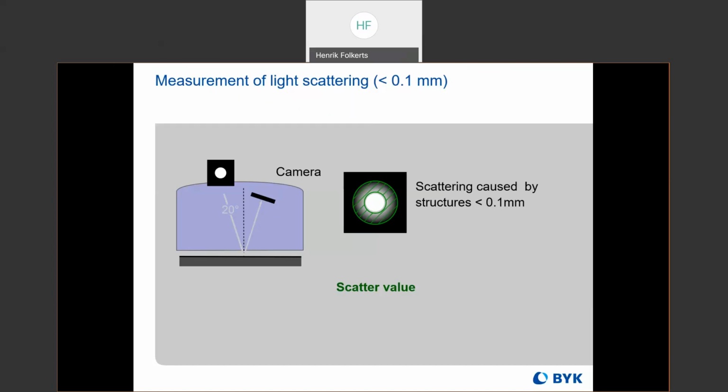So if you're looking at one scale and the numbers are saying your surface looks good, but you can tell that it doesn't look good, often you need to start looking at some other scales that are going to tell you a more complete story about the surface. And I have to say, or vice versa, if your surface looks good but your number's bad, then you really need to look at the structure spectrum, and you can totally send the data to us and we can look at it.